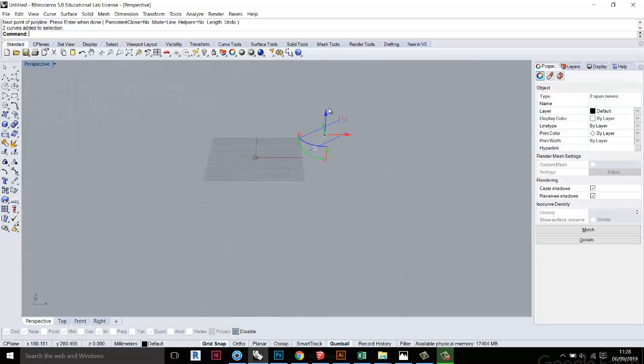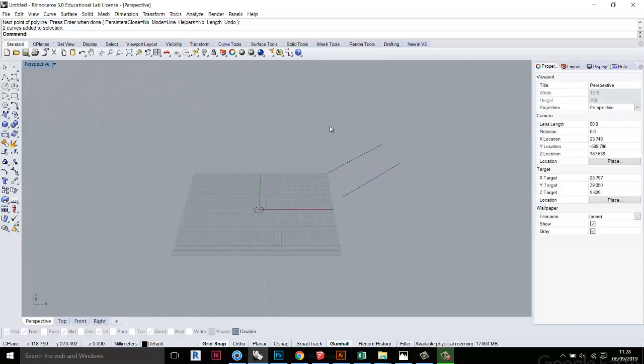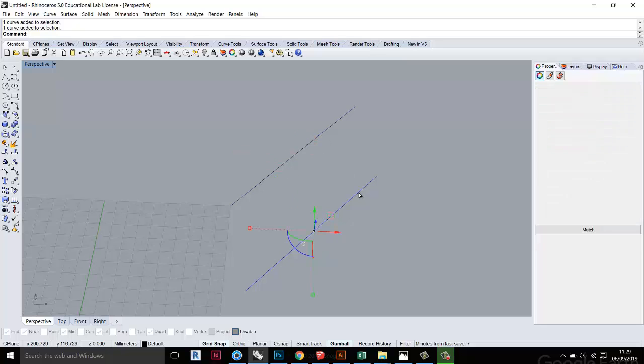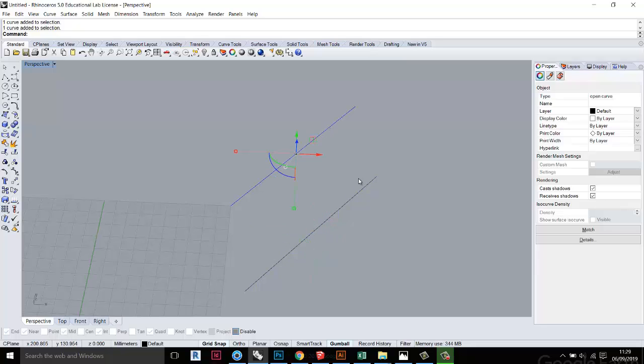So we'll quickly talk about selection. If you've not been following along, use some of these tools to just stick a bunch of shapes on the screen, because we need to select things next. So selection works in a couple of ways. You can select by just clicking on objects, but if you notice, if I just click on the next object, if I was trying to select both of these and I'm just clicking on them with a left click, I'm deselecting the first one as I'm reselecting the second one.